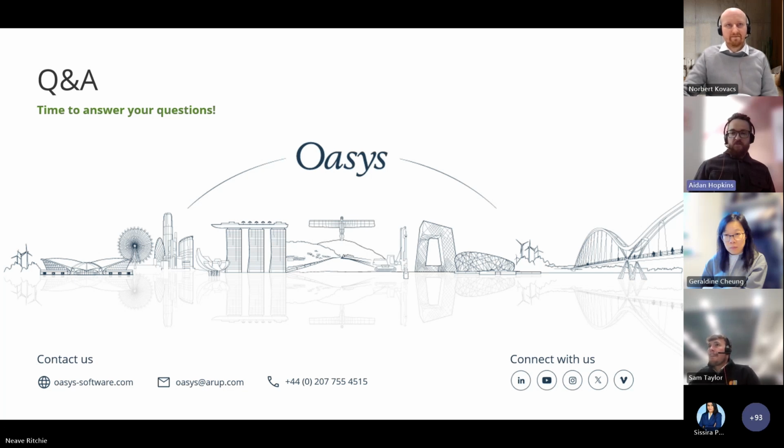From my perspective, on the first part of the question, if you have a stage model, the XDisp summary does give you the summary of the worst case for the stages. So it will tell you in stage 4, this was the worst case. That's pretty straightforward, doesn't require too much effort. In regards to contours from tunneling, if you've got one tunnel, in terms of setting your zone of influence, the final contour does set the area.